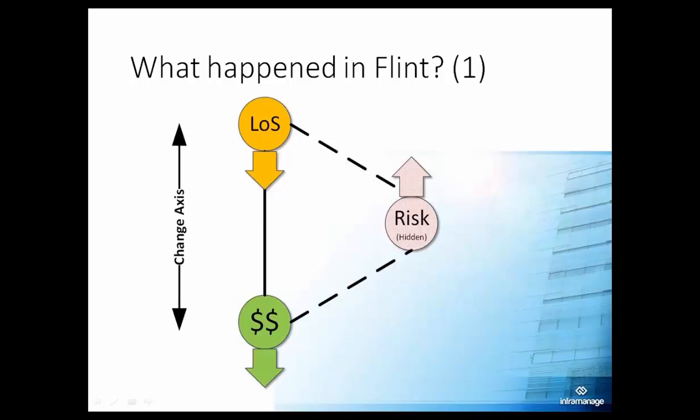So, if it's a huge problem in your utility, like if there are tons of people for whom it supplies, it is actually one reason that electronic read meters can be used, because you can start to track the background leakage in each person's home if you have those nighttime readings, because they'll give you some idea of, okay, this background amount at night is probably the leakage in the home, and you can provide that information back to the customers and indicate to them that it is costing you this much on your bill, or you're actually leaking 2,000 gallons. It is expensive to put those automatic meter reading systems in place, so you don't take it lightly, but if you really need a way to address inside the home, it is another tool that you can consider.